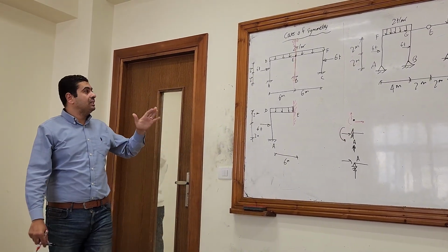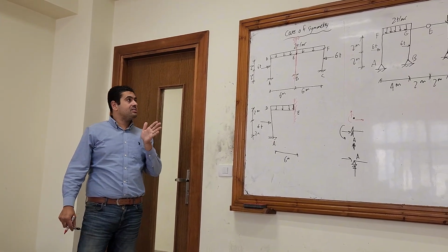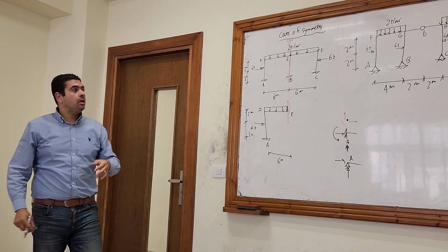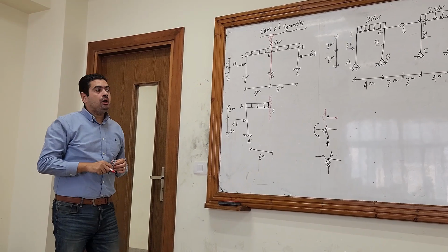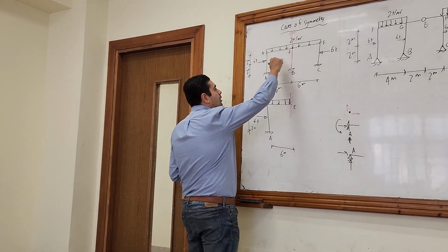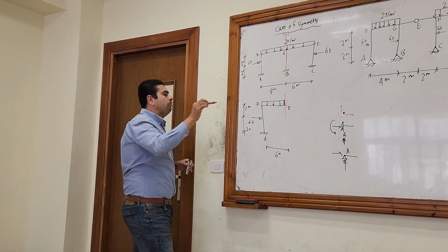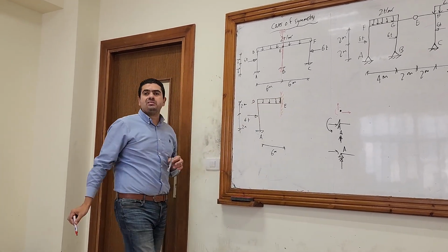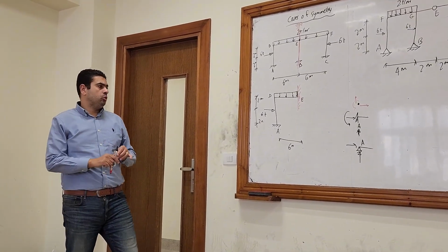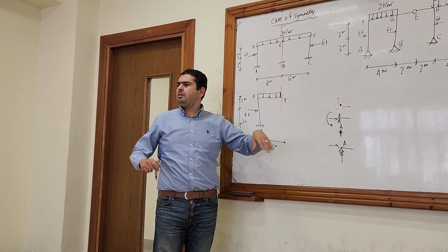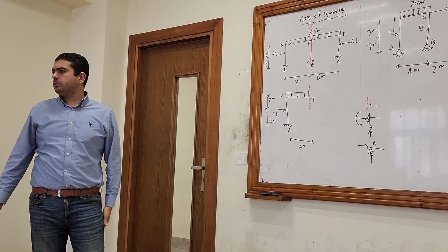So when you find a line of symmetry above a frame member in a symmetric frame, you can draw only half of the frame. You can remove the vertical frame member BE, and you will put at point E a fixed support. That is a rule. You don't have to think about the displacement one more time. I'm just explaining why I put a fixed support here.